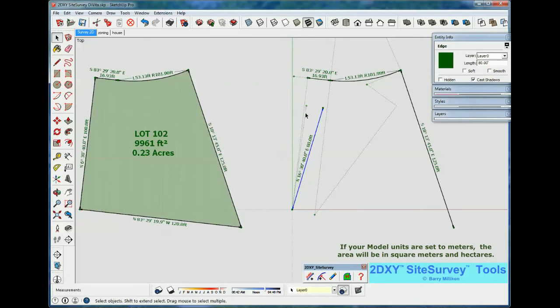And this dotted construction line shows you where it was. So what I need now is to move these elements to connect to that new location of that bearing. If I select the first one and right-click, select all connected, that selects this entire string of elements, the first bearing, the arc, the second bearing, and all of their dimensions.